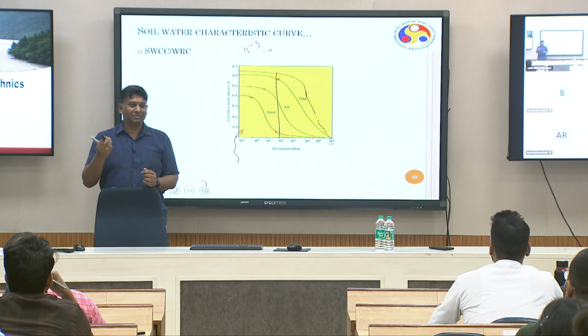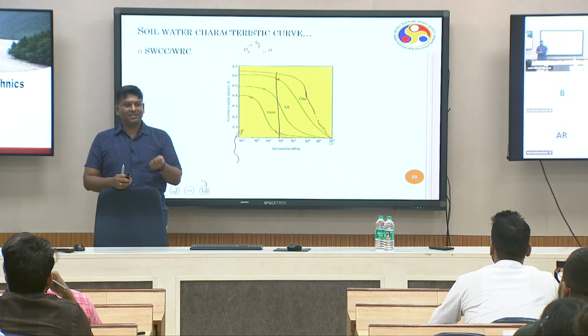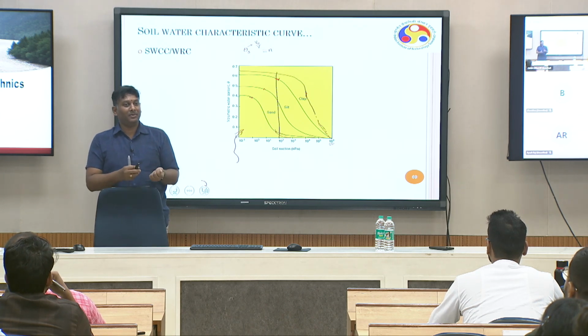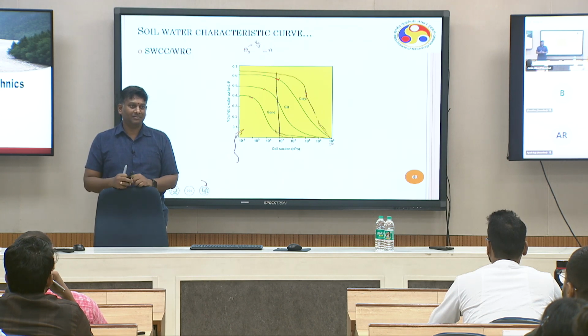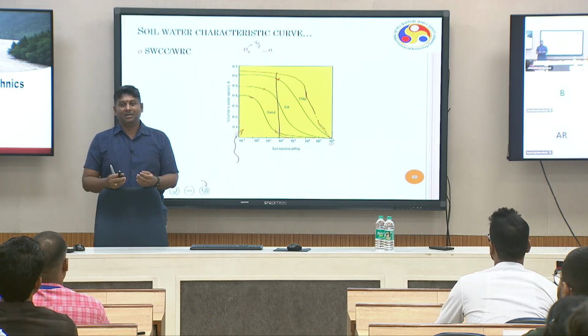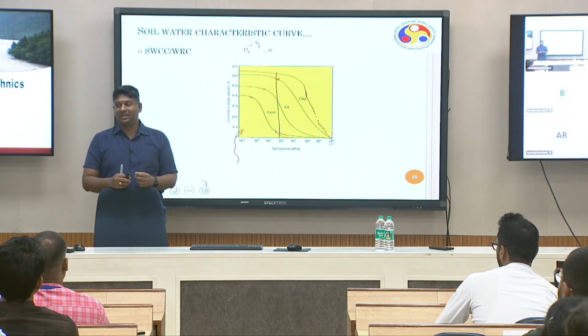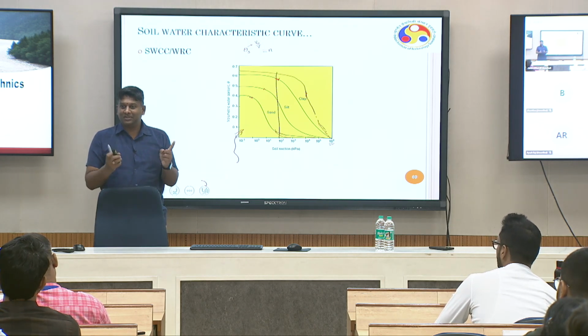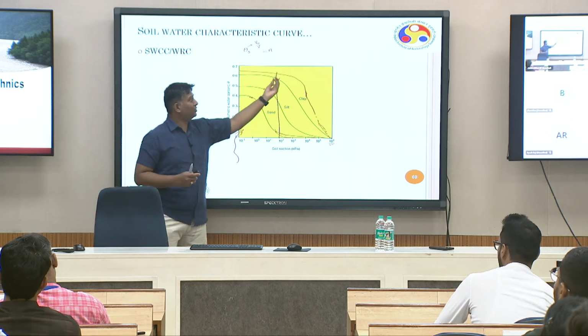Yesterday there was a discussion with Bhargav about plants and the wilting point of plants. Plants have a certain capacity to draw water. If the capacity of the soil for holding the water exceeds the capacity of the plants to draw the water, then they wilt. In black cotton soil or expansive soil, most plants would not survive for the same reason, because the soil has higher potential. So it will not give up water that easily. If you plant something which cannot take the water because of the suction difference, this soil has a very strong potential, it will not give up the water.